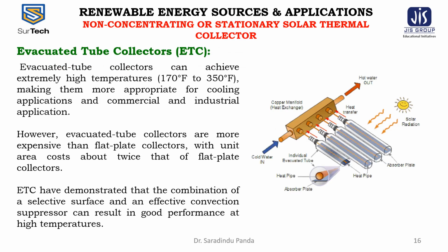Come to the second type, non-stationary collectors, that is evacuated tube collectors, ETC. Conventional simple flat plate solar collectors were developed for use in sunny and warm climates. Their benefits, however, are greatly reduced when conditions become unfavorable during cold, cloudy and windy days. Furthermore, weathering influences such as condensation and moisture will cause early deterioration of the internal materials, resulting in reduced performance and system failure.